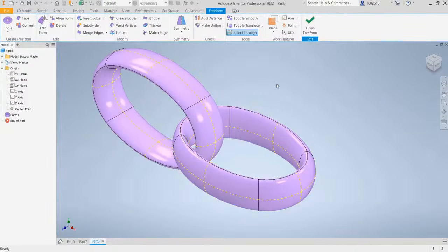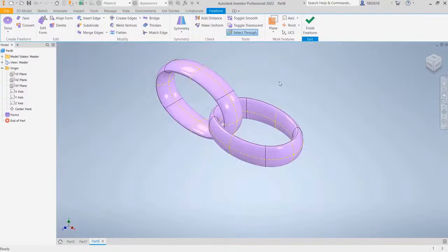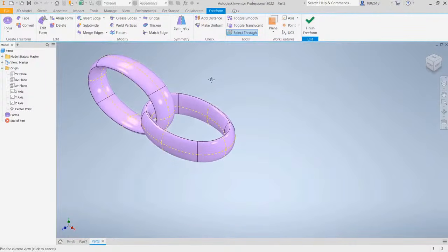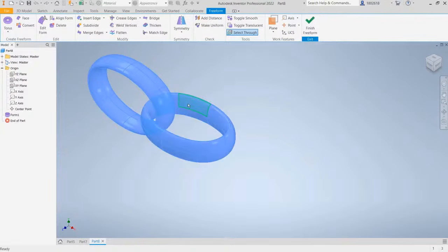Zoom out our view using your mouse wheel. Then drag it to the left side. Then we need to copy these two figures in order to complete the chain. Just double click this figure. Then press Ctrl to select another figure. Double click. Then press Ctrl on your keyboard for the copy command. Then press Ctrl V to paste.